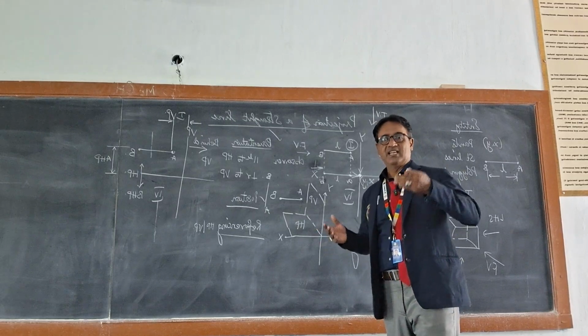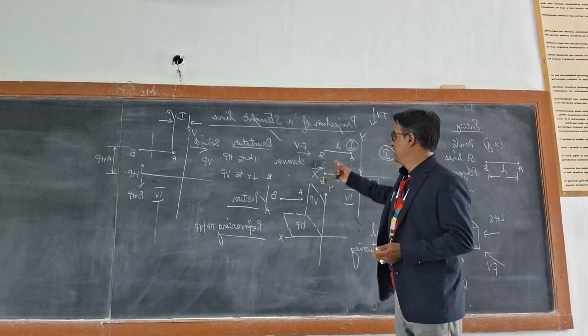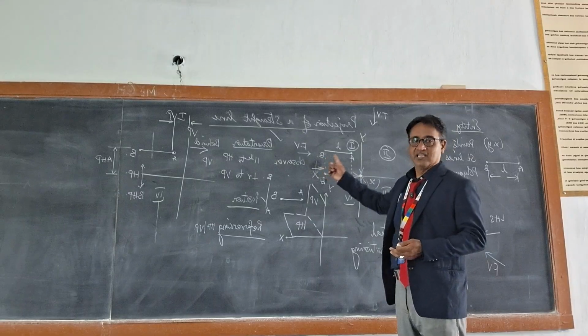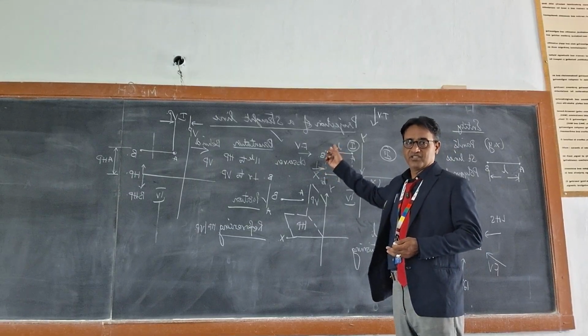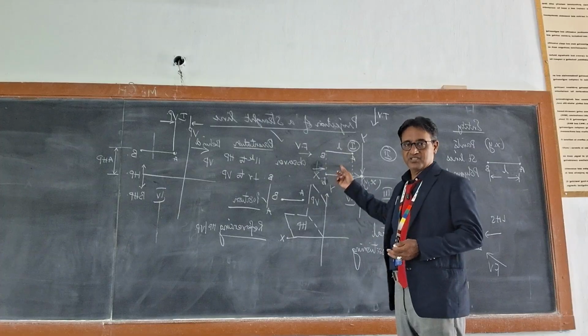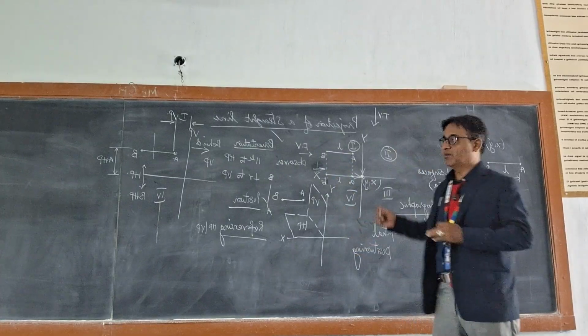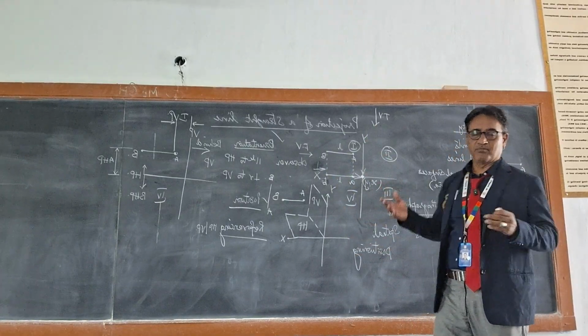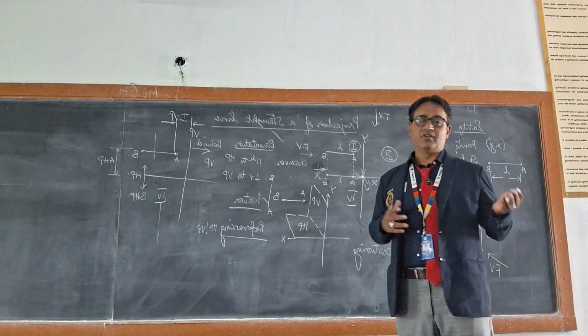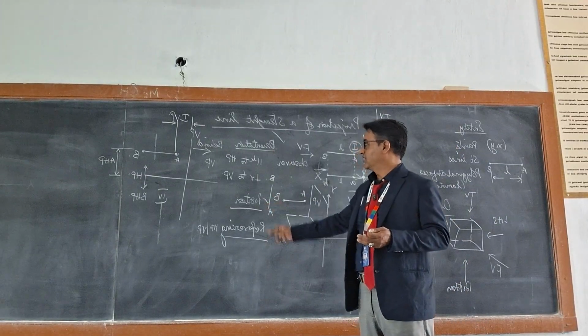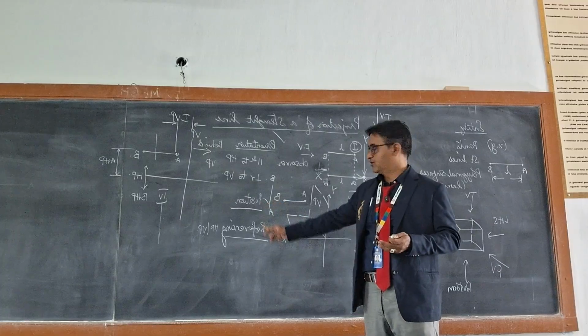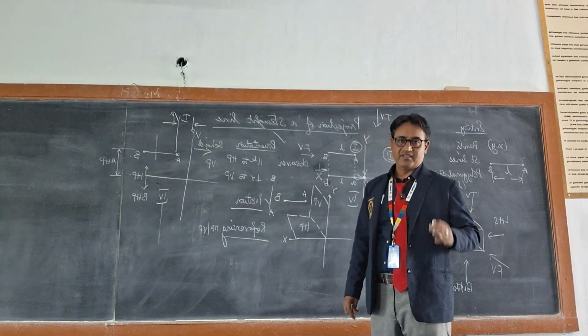All the definitions of the object, say here point A and point B are the definition of the object, and length is also a definition of the object. So all these definitions will be projected onto a perpendicular plane, whether that plane is the horizontal plane or the vertical plane, depending on the three different conditions. One is orientation, the second is positioning, and third is referencing.